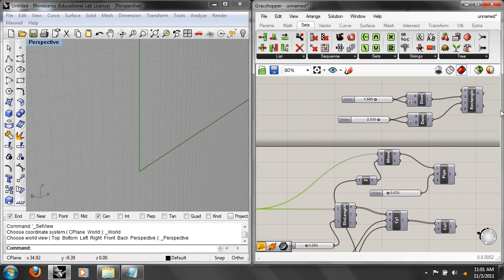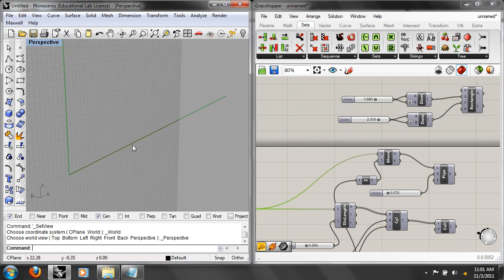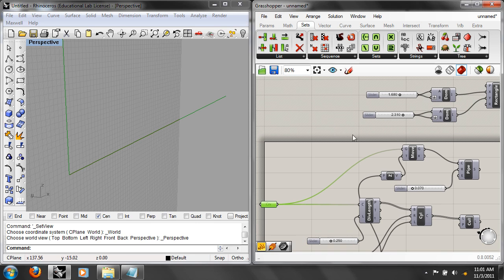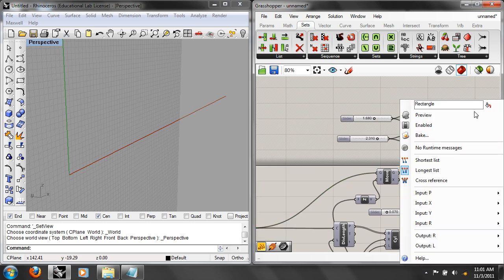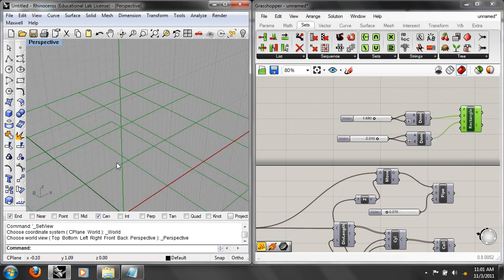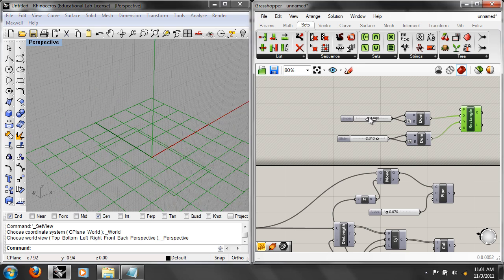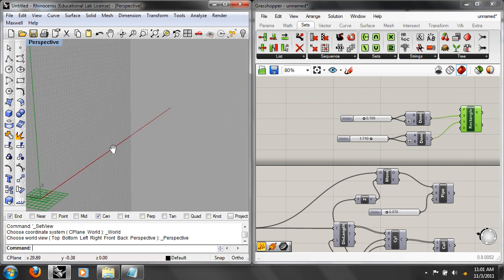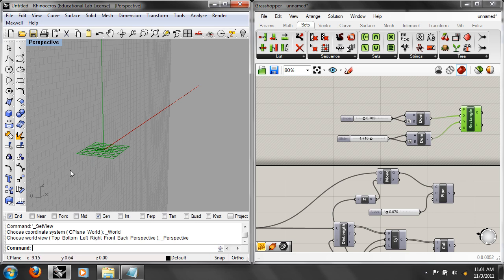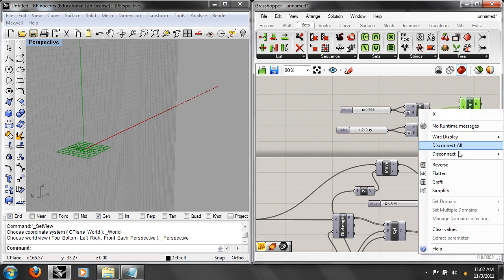So what you want to do is take a rectangular section and put cross sections along here, and then basically, it's sort of like a loft. We would loft across here, but instead of a loft, we're going to do what's called a rail sweep, and a sweep is like a loft along a particular curve. Okay, so let's look at that. But in order to do that, we need to get the rectangle, which right now is the shape that is like at 0, 0, 0. Right? It's this kind of thing. And we want it to be oriented to this line that we made in the ZY plane. We want that to be sort of like perpendicular to it. And luckily, there's a way to do that that's really easy.